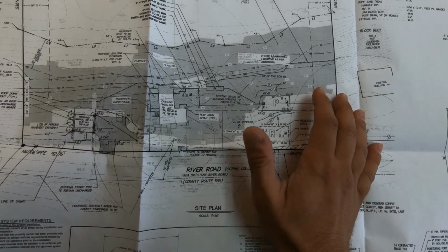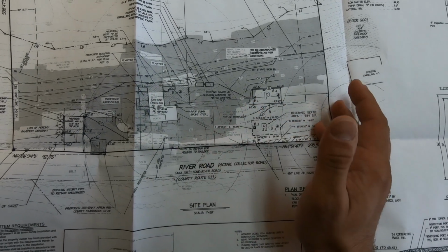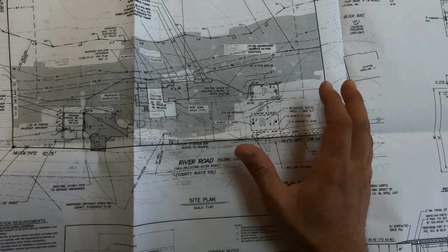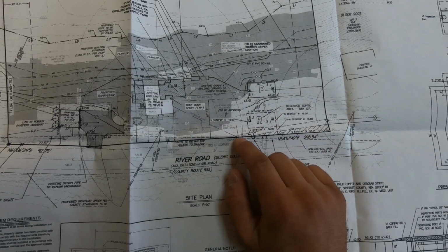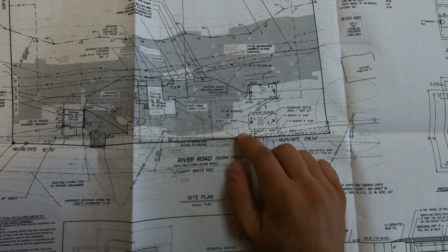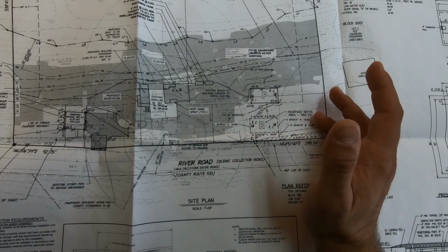Usually, ideally, we use a building corner, some type of benchmark, or a property corner if that's available. We've also used telephone poles in the past, utility poles. Those work pretty well. But you want something permanent that's not going to move over the years to tie down where the features are on your septic field.